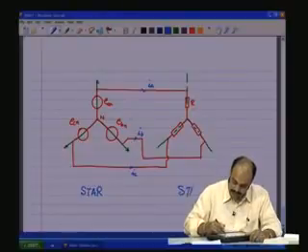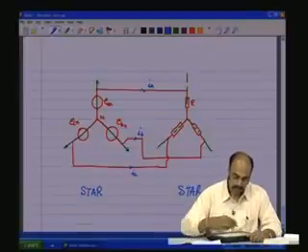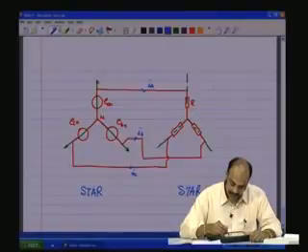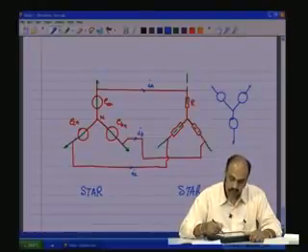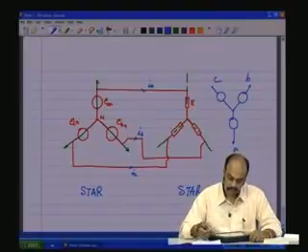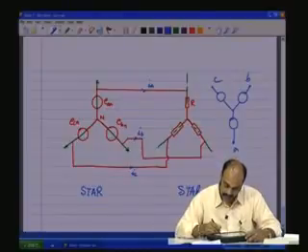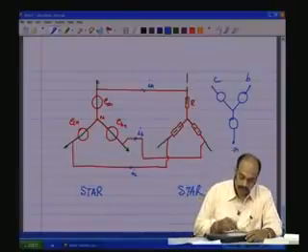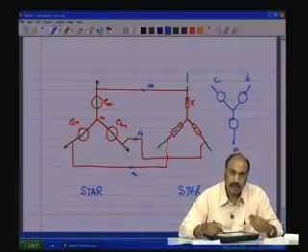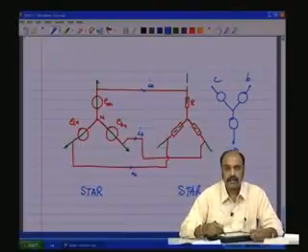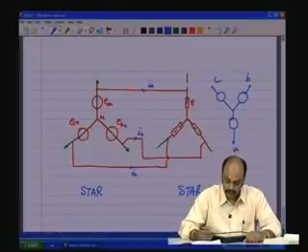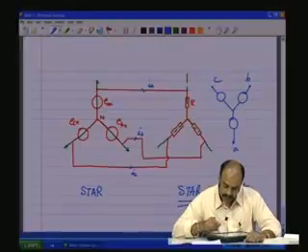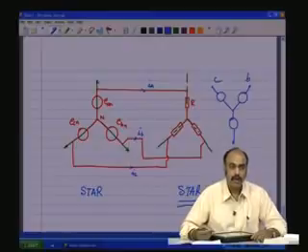Star load is also in the star form, and if it is in the inverted way, in some cases the circuits may be written in this form. Here the A, B, C. So, this looks like a Y, and this is called a Y circuit. For this type of circuits where you have one end of the sources or the loads connected, joined together, common, and the other 3 terminals are taken out and used for connection to the source or the load, such a connection is called star or Y connection. So, this is a star or a Y connected circuit.